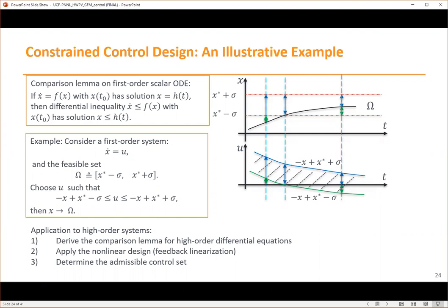And what this allows us to do is to balance various requirements. While we're trying to control the active and reactive power, we need to also look at, for example, how voltage and current are going to change. And conversely, when we control the voltage, we need to look at how current is going to change. And this allows us to basically optimize against a set of objectives, not just a single control design.